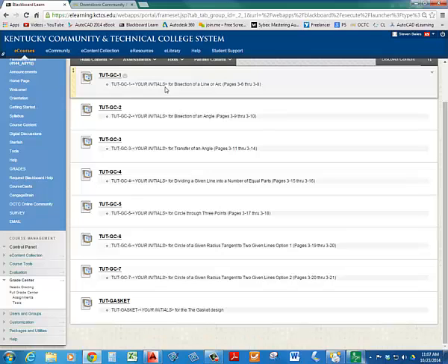We use a command that we can just offset it the thickness that we want, which in this case is a 1/2 inch, and it just makes a copy of it smaller, automatically scales it down. Okay, so you'll create that, and that'll be your TUT-gasket drawing. So there's 8 total tutorial drawings that you do.